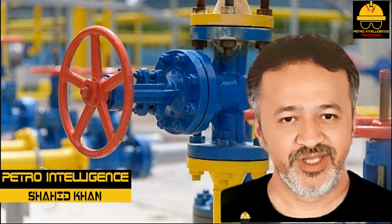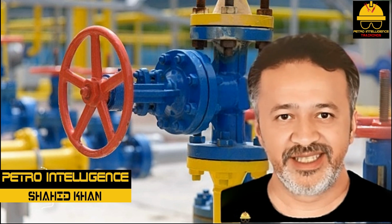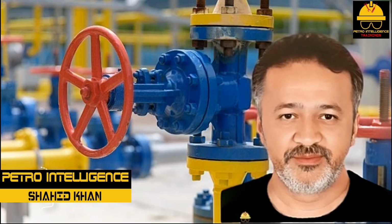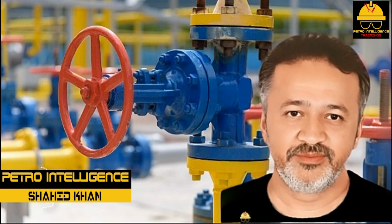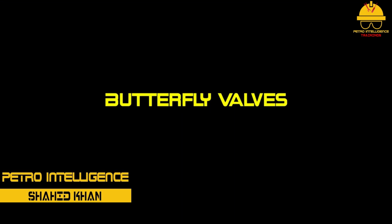The specialty alloy check valve is used in high temperature and high pressure services. Some common alloys used are nickel and iron or steel and titanium. The bronze check valve is used in low pressure and low temperature as shown in picture. The brass check valve is used in low pressure and low temperature. The cast iron check valve is used in water lubrication and some low pressure steam services.